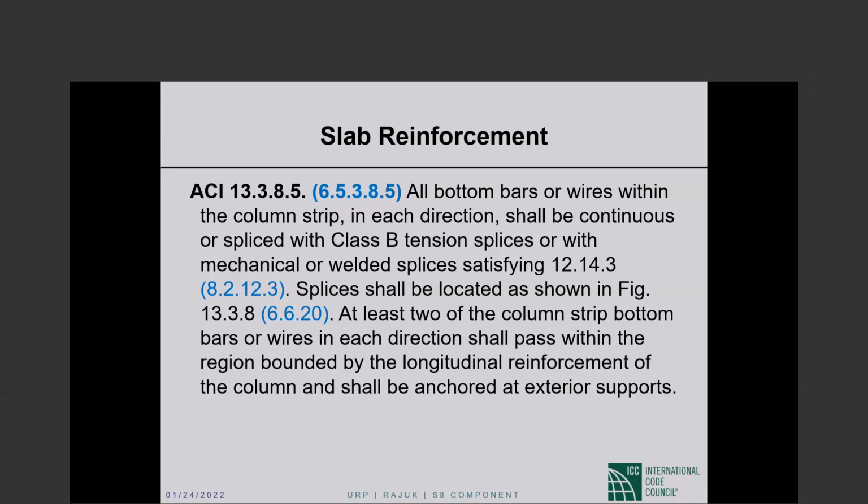The idea is if there is extraordinary loading or a column gets knocked out or something, the slab should keep on hanging in place. It is not expected that everything will be the same as before the column got knocked out, but our expectation is that the slab should not end up on the ground or on the floor below. It should be hanging in place.